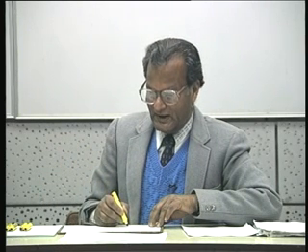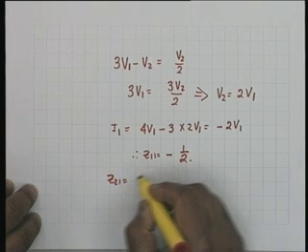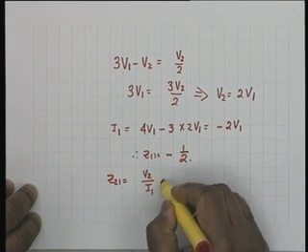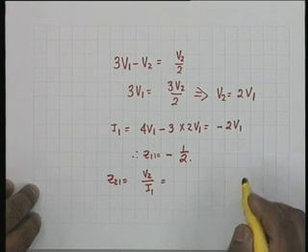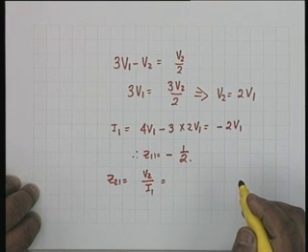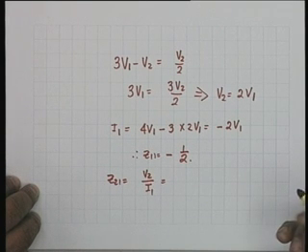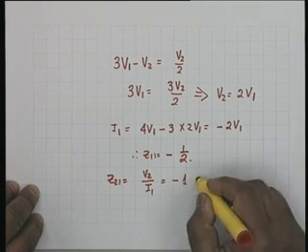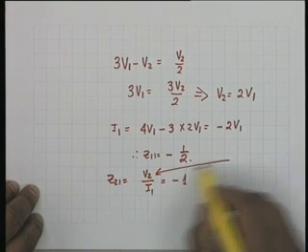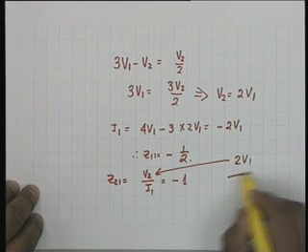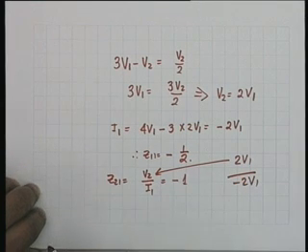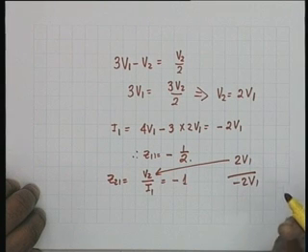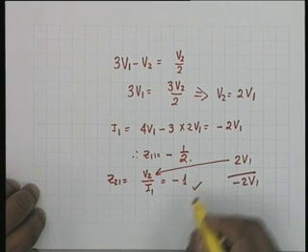Wherever negative resistance occurs, instead of dissipating energy, it generates energy, and therefore the circuit is an active circuit. Number 2, I want to find out Z21, which is equal to V2 by I1. It is simply V2 by I1. Minus 1, that is right. How do I find this? V2 is 2 V1 and I1 is minus 2 V1. Everything is expressed in terms of V1. So, Z21 is equal to minus 1.